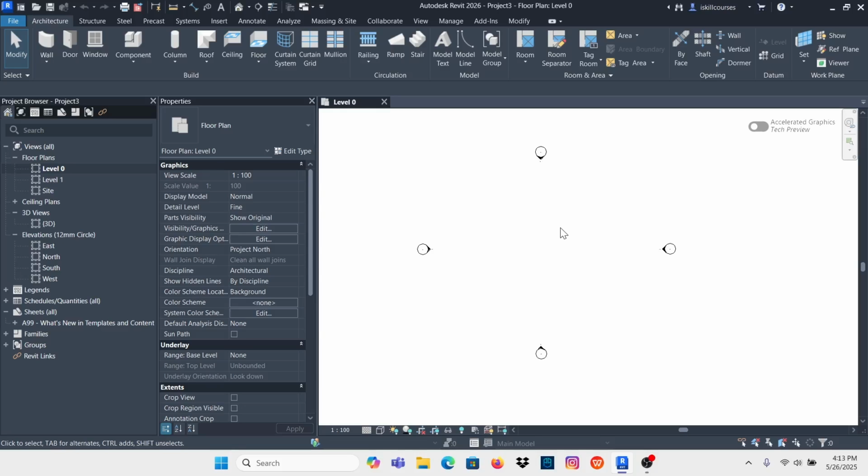Okay, now I'll get started. And to get started in Revit, don't be intimidated by what you are seeing here. As we go on, everything will become very, very easy for you. So we need to start by creating our levels here. So you just need to go to any of the elevations and open one by double clicking. I'll go to south.